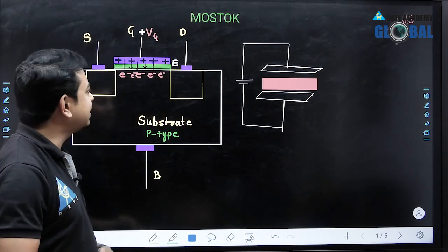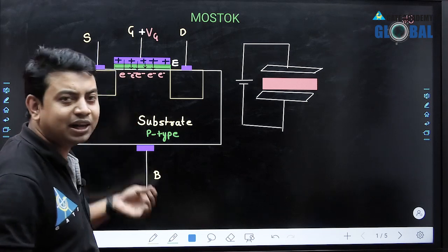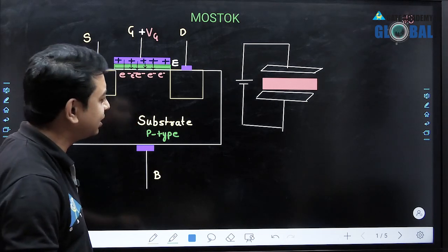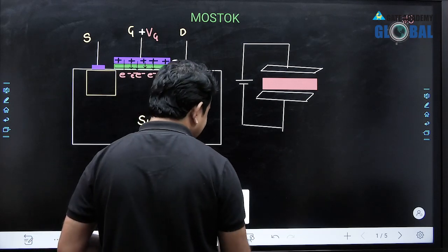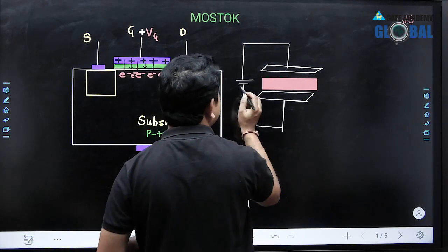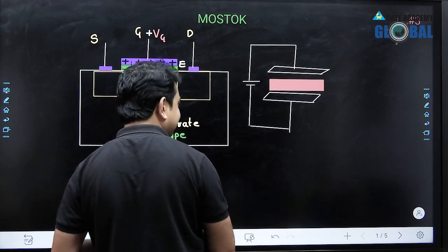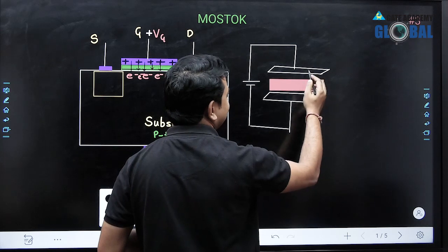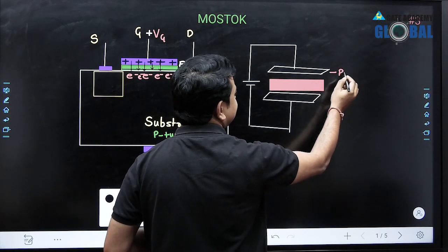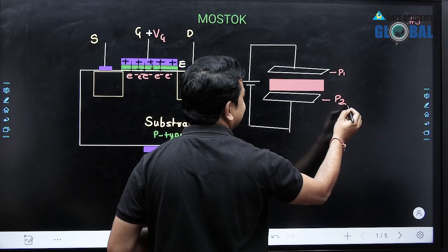We can watch this dielectric, present in green color between the metal and semiconductor, that is nothing but silicon dioxide in the metal oxide semiconductor. When we apply an external potential, it is no longer in equilibrium. Initially it was in equilibrium and must be neutral. This is plate 1, which is neutral initially, and this is plate 2, which is neutral initially.